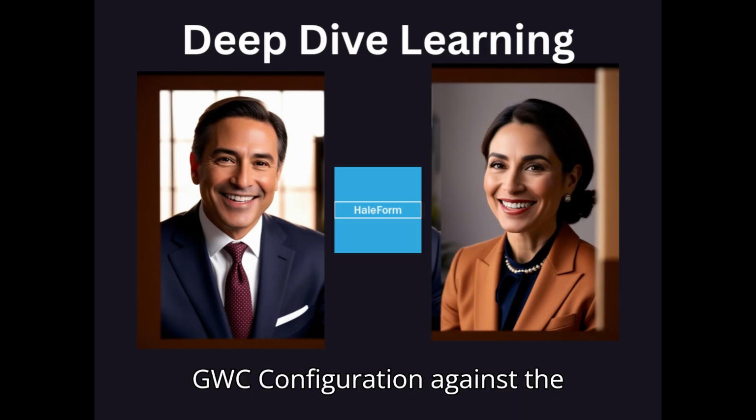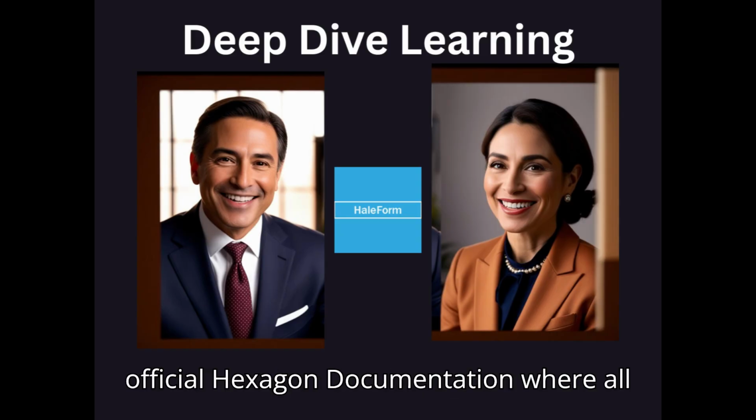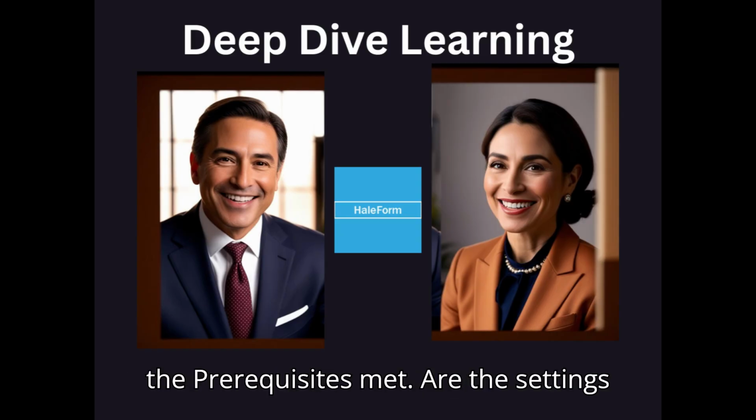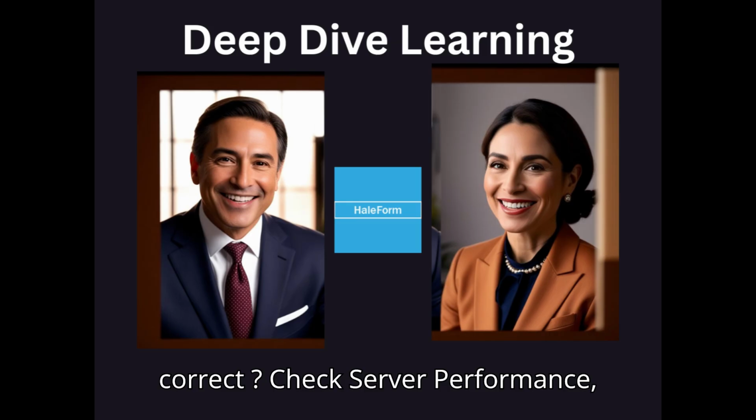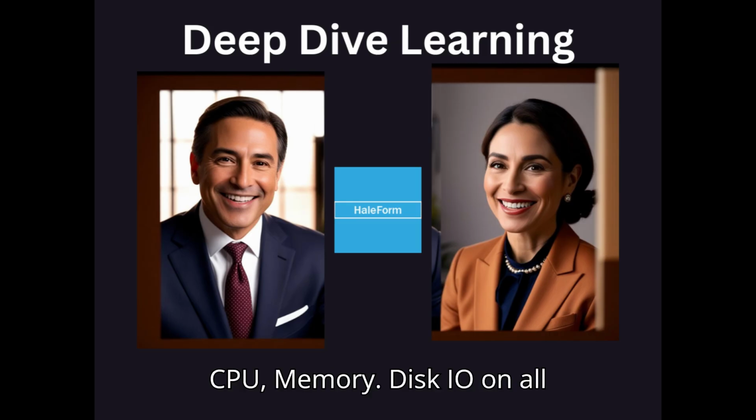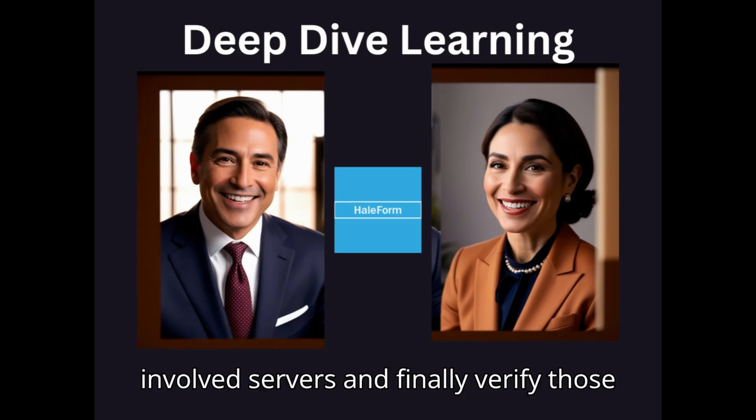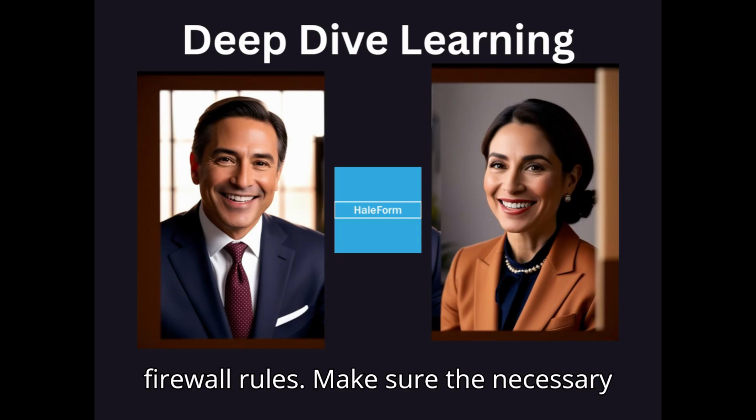Also, double-check the GWC configuration against the official Hexagon documentation. Were all the prerequisites met? Are the settings correct? Yeah. Check server performance, CPU, memory, disk I/O on all involved servers, and finally verify those firewall rules. Make sure the necessary ports are open.